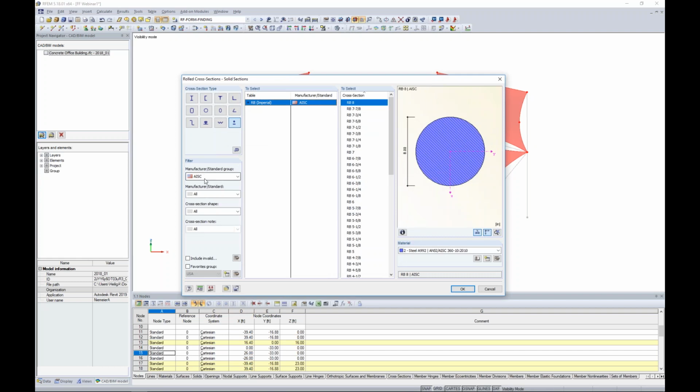In particular, today I'm going to use the solid sections. This just has some pre-populated diameters. They're basically just round bars populated from the AISC with set diameters, but you can always create your own with a parametric section. We'll choose a 1/2 inch diameter cable.